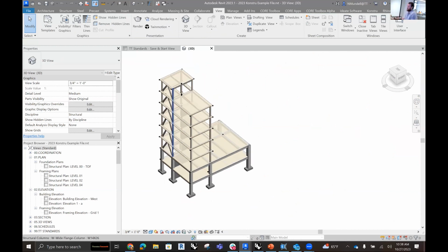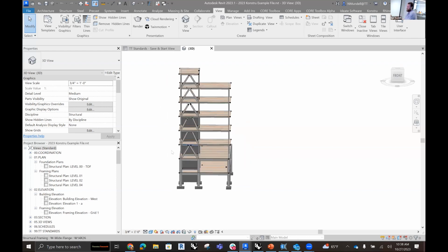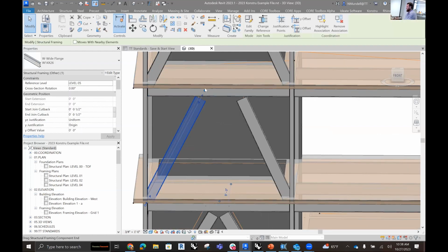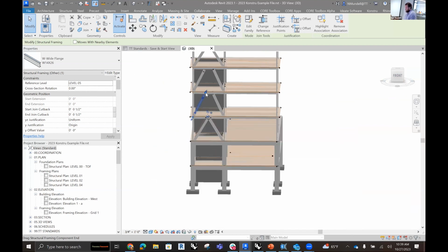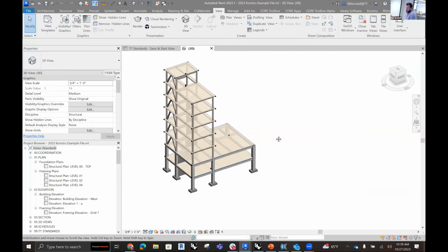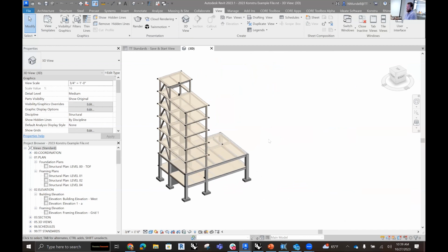So if I was translating from Revit to an analysis software, which we're going to do now, I would want to make sure that the geometry was as well connected as possible. However, if I was translating from Revit to Tekla, where the steel gusset plates were going to be detailed, then I would want to make sure I was able to extract from Revit the blue dot positions, because that is the relevant end coordinate for a steel detailing model. All right, so Konstru can extract both. In this case, because we're going to analysis, we're going to repair the analytical model.